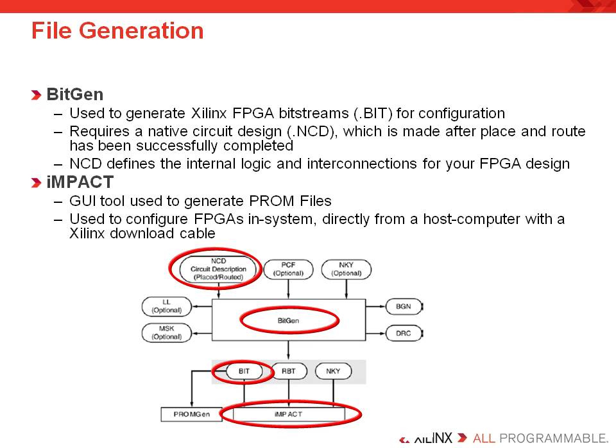Likewise, the NCD is an input to ChipScope, which is used to debug a design, as well as various other reporting utilities, even the PlanAhead software if you want to control layout. So the NCD file is really everything about your finished design. It's a very key file because it's used as an input to so many other analysis utilities.